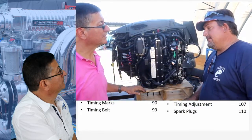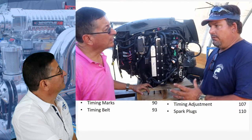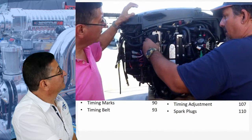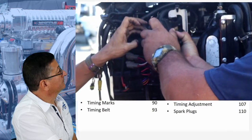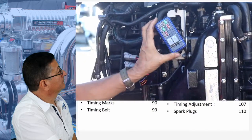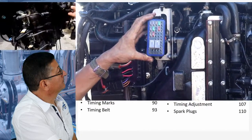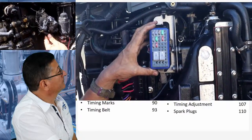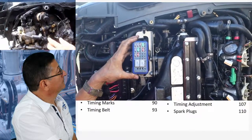Well, if the fuse is blowing, there's a reason why it's blowing. You have to figure out what the problem is. So obviously this is a fuse panel here, and we'll take it off real quick. Okay. And there's your fuse panel. So if you took this 10 amp and put in a 20 amp, if you look at the picture above, that's your result. This is the consequence. And that's what happens. So you should never put a bigger fuse than what it calls for. There's a reason for it.